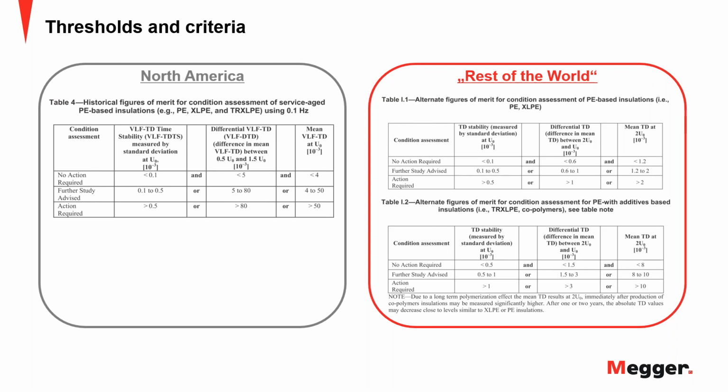On the other side, if people have very important cables, like special circuits to hospitals, where they have to guarantee a service level, they have to do both tests because they need to know: is my cable in jeopardy because of the aging condition, or because of some bad component or a localized defect that can fail the cable? So that maybe answers your question, okay? It all depends what it is that you're trying to do. That determines